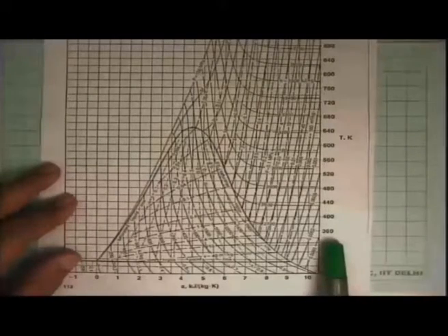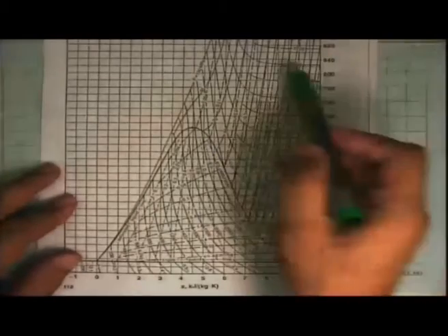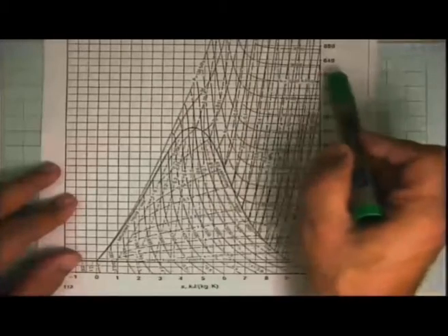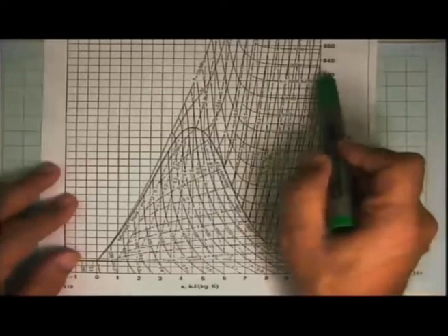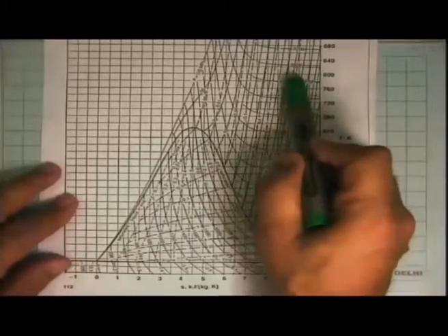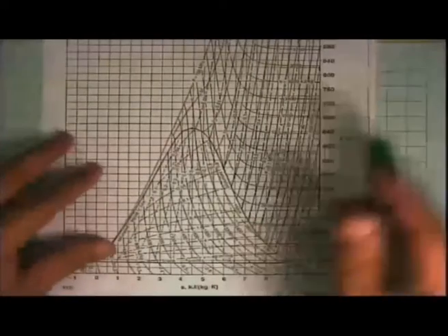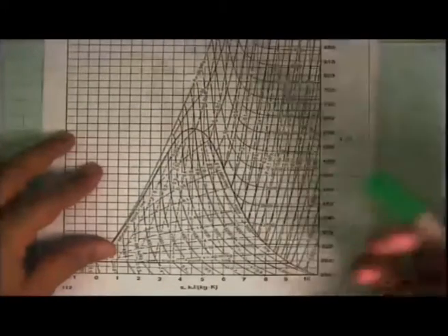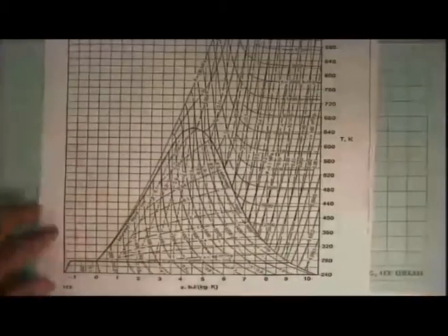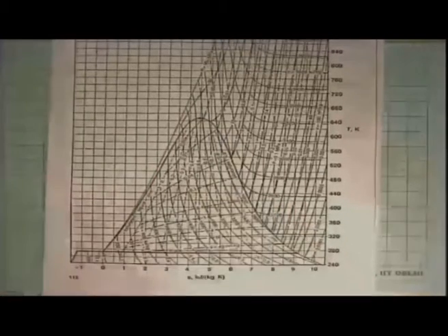And in a minute we will see why these H lines have become horizontal, which means that H is now 3500 at this particular temperature. So if you pick up any pressure, that doesn't matter, specific enthalpy is the same. It is independent of the pressure, and that's what ideal gas behavior actually begins to look like. Okay, so this is the thermodynamic properties of water.